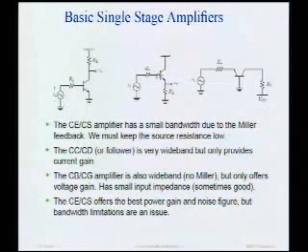That's because the voltage across the nodes are almost equal, so very little current flows into that capacitance, and therefore it's very wideband. Another way to look at this is the input impedance is highly degenerated, and so that feedback, the degeneration produced by RL, is basically going to reduce the input capacitance.